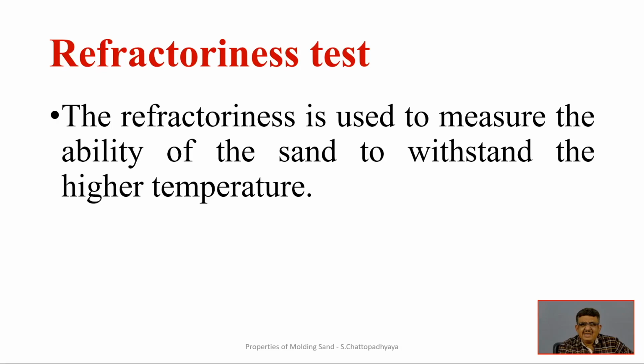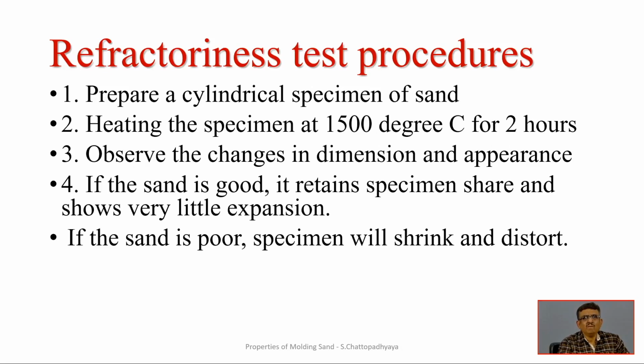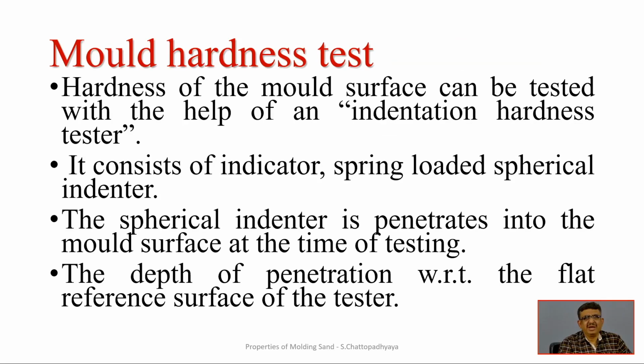The refractory test is used to measure the ability of the sand to withstand high temperature. I have already mentioned that this property is important to retain shape and size even at elevated temperature, in the vicinity of the liquid molten metal. It is also a standard procedure: a cylindrical specimen is heated, the changes and temperature are observed, and on that basis the conclusion is arrived at.